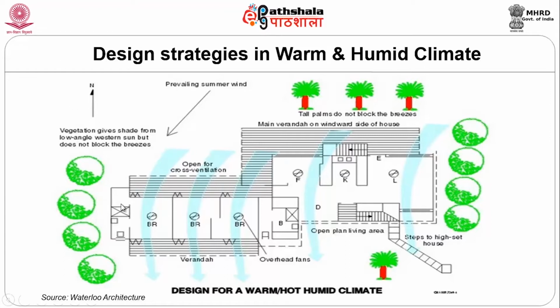So, if we have north, we need to make sure the west is blocked, because west is where the sun sets, and we have a lot of heat coming in from there. We need to have open areas around with a veranda for cross ventilation and an open plan for the living area. Tall palms do not block the breezes, and there should be a main veranda on the windward side of the house. And we need to have steps to high set the house or tilt the house, which means that you are going to bring air and breeze into the house.